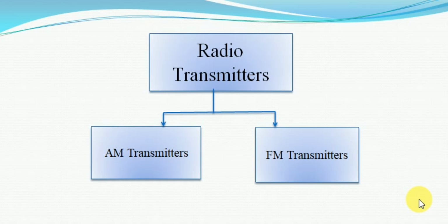In this way, I will use a low frequency crystal oscillator circuit in order to get a better desired carrier frequency in FM transmitters. So finally, we can say that in order to obtain good frequency stability in the transmitter circuits, we have to use crystal oscillator circuits depending on the frequency range we are using.